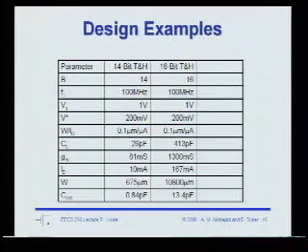Quickly redo that calculation to get an extra 2 bits, and you see a huge difference, right? You'll notice that you have to pay more than 16x in current to get that extra 2 bits, and that jives well with the calculation we did earlier where we found out that every bit costs us 4x in power.